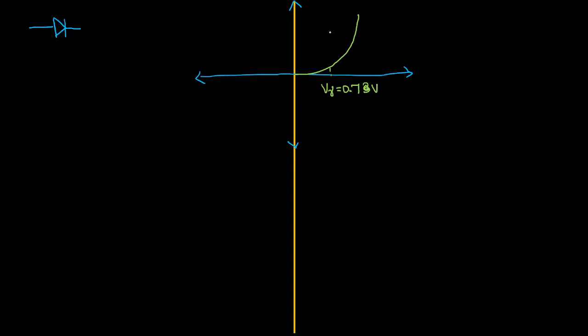So this is forward bias, and the y-axis indicates the current flow through the diode. The x-axis indicates the voltage drop across the diode. Similarly, in the opposite direction, this is negative voltage or reverse bias, and this is negative current flowing through the diode. The moment we inject positive voltage through the diode, this is the characteristic you can observe. The maximum voltage drop across the diode will become 0.7 in forward bias. That's all. Then it will turn on. It starts carrying a huge amount of current, up to its maximum specified rating.